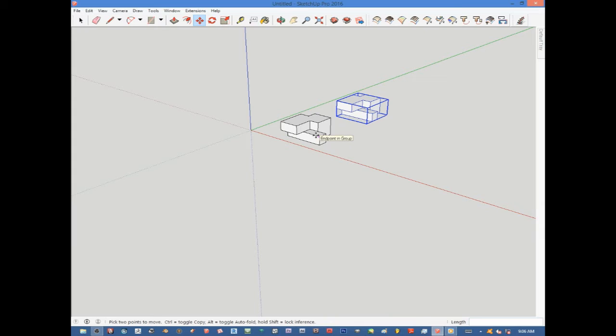I'm going to try to explain that copy again. Control Z, that is undo, so that I'll explain again. If I want to copy this object, what do I do? The first thing I do is pick my move tool over here. I press Control down. You could press Control C if you like.